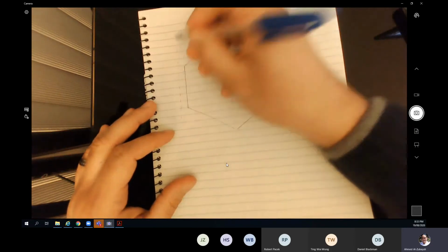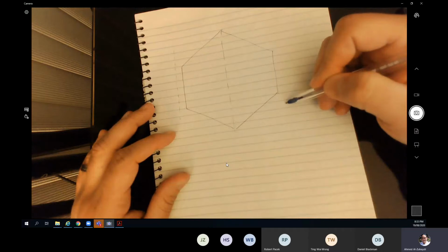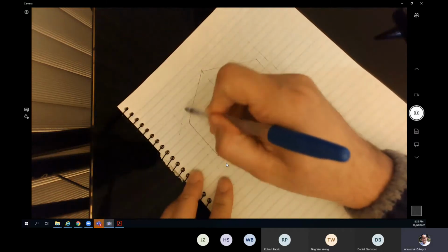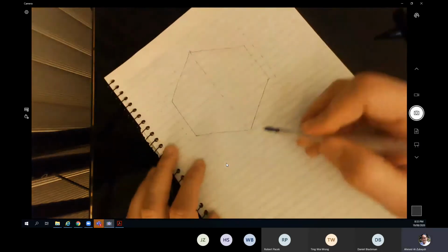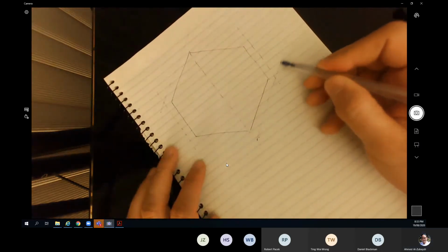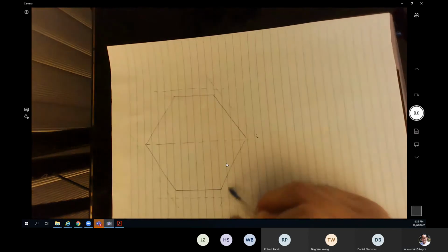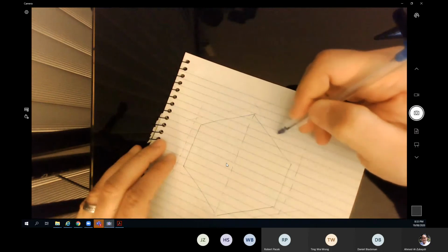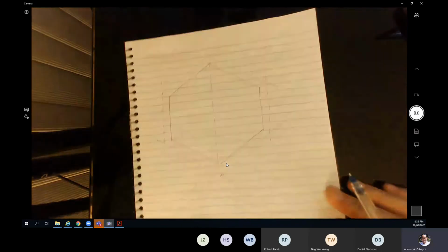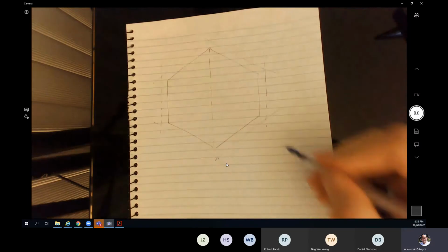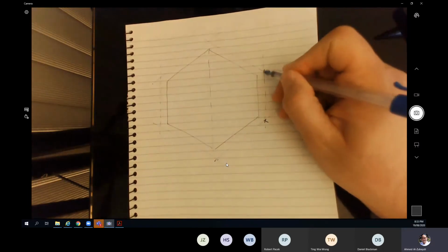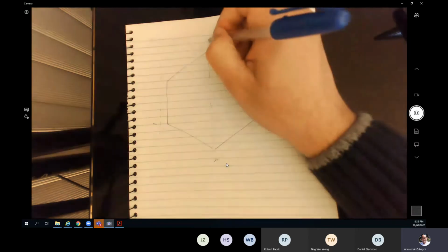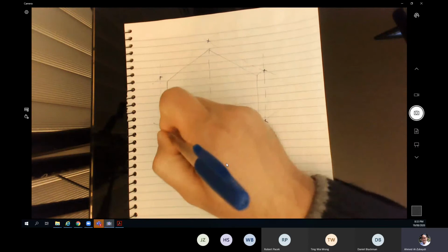Oh, we use the same 12 millimeter diameter tool. So we make a line which is going to be offset by 6 millimeter and have the intersection lines here. This will be my toolpath. The trick we're going to have with the toolpath is when I'm going to find these points, just remember that these points is going to be in this direction, not horizontally. So we need to do a simple calculation to find the location of that point.